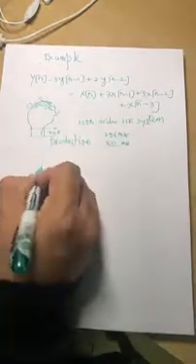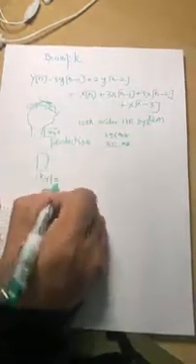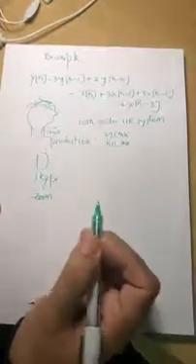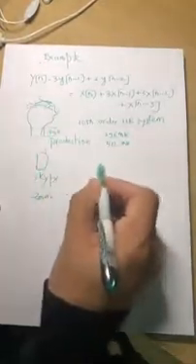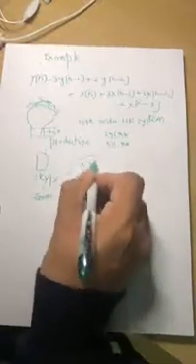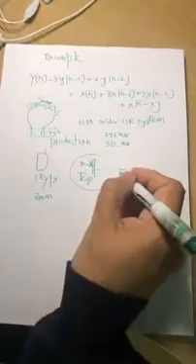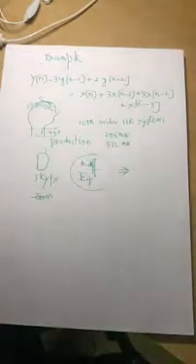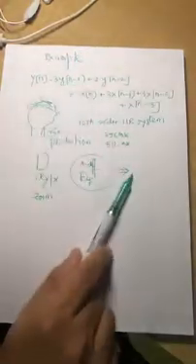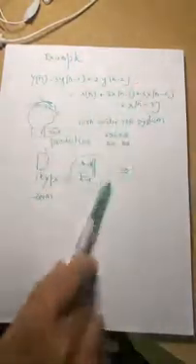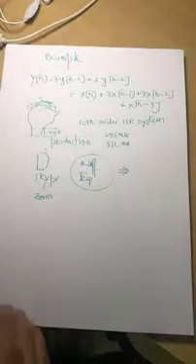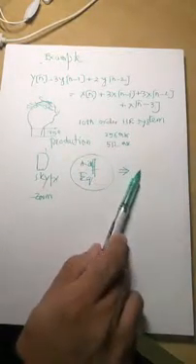Once your mobile phone or your Skype or your Zoom is sending voice, it is not sending voice, it is sending a difference equation, and that's how you save the bandwidth. The same is the case with MP3 songs. The voice is modeled as a 10th order IIR system, and the receiver takes the 10 coefficients and then produces voice for you.